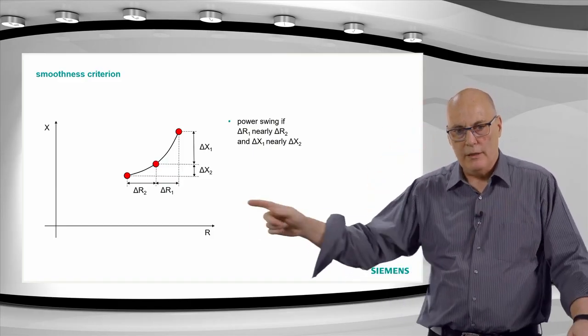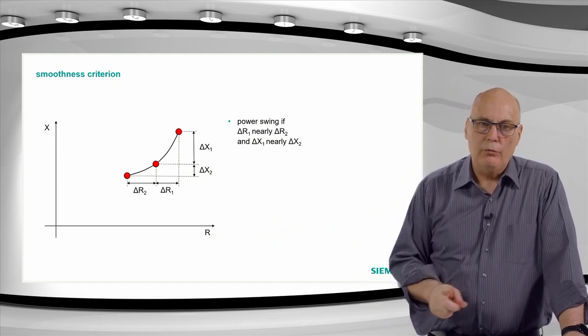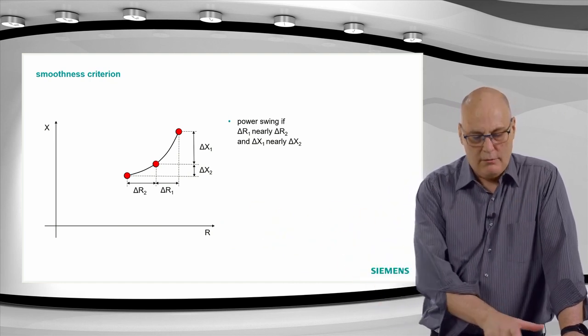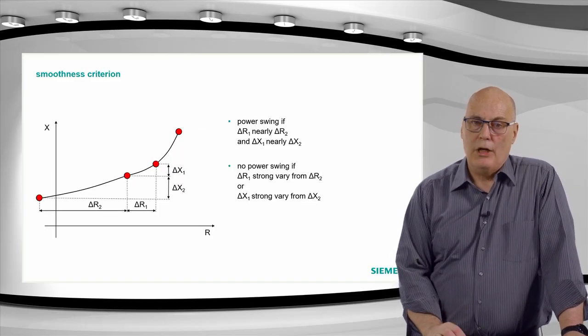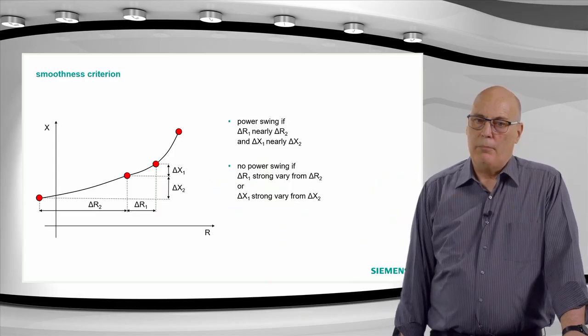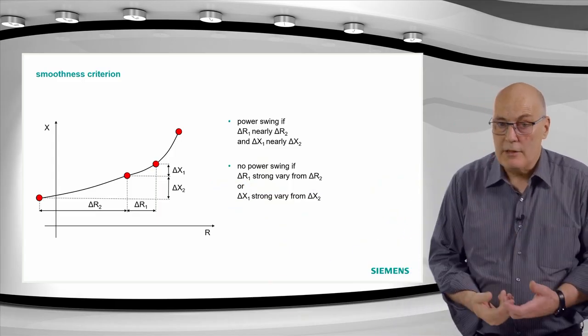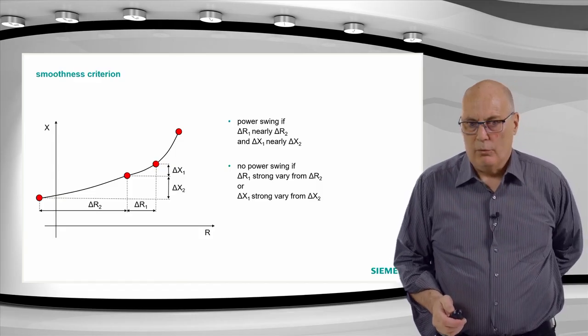So for the relay, the power swing impedance trajectory movement is fairly constant, fairly slow, but it must be continuous. It cannot jump. It cannot be slow and then all of a sudden have a rapid jump like that. That is not possible. That would be a reset. The jump of the trajectory would be a reset criteria for power swing blocking.